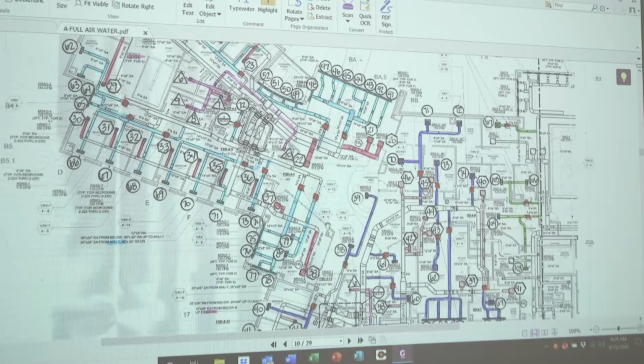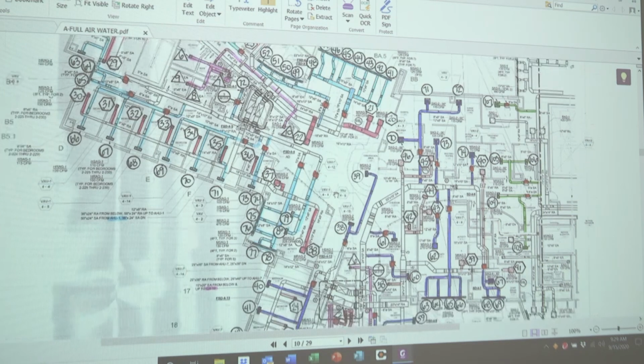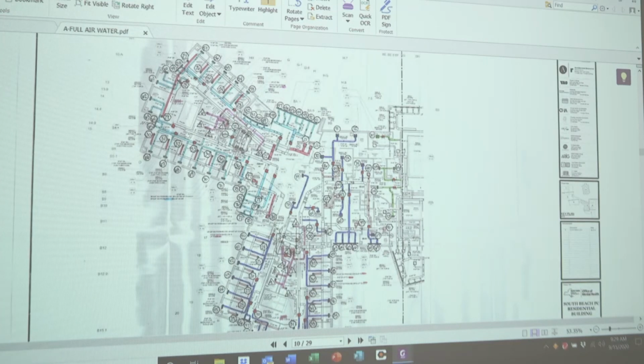This will allow you to realize quickly where these boxes are, what their number is, and what air handling unit it's associated with. This is typical throughout, and becomes consistent on all the floors. You'll see that this is air handling unit number 1. All these VAVs will be provided with a VAV number 1, a floor number, and a unique number.